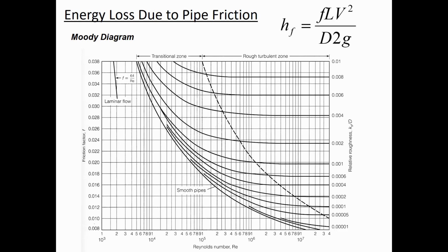So epsilon is 0.26 millimeters. If this pipe diameter is 500 millimeters, then what we'd need to calculate is the ratio of that equivalent roughness to the diameter of the pipe. So 0.26 millimeters divided by 500 millimeters.